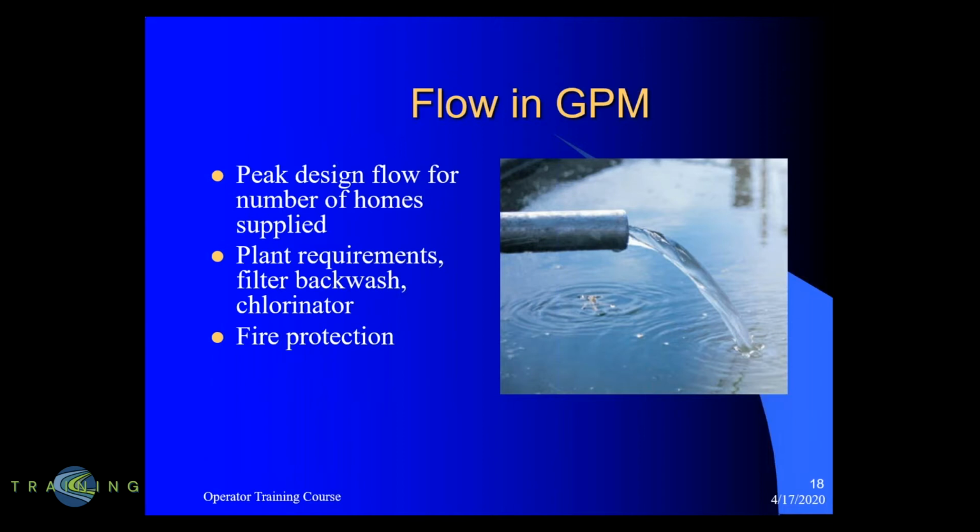in order to be able to provide that flow rate to your filter properly. Maybe you're in a high service pump and you've decided how much flow you need to pump to the high service tanks to fulfill your requirements to the community, or a chlorinator to pull a vacuum, or fire protection where you need either 500 or 1,000 gallons per minute. But the point is that flow is about the process, not about a calculation. So we usually look that up in tables.